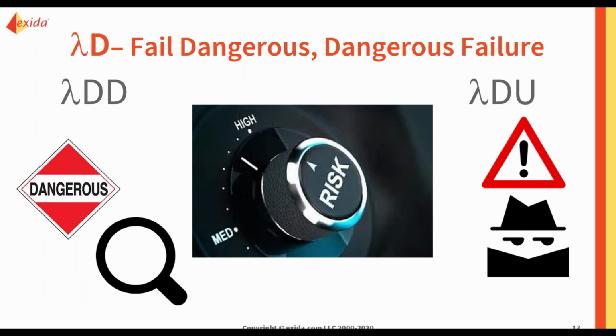Well, the dangerous is where you can't do its job. Your SIF can't jump into action if needed. So a dangerous undetected would be some type of failure that prevents the safety system from doing its job when it needs to, and it was unnoticed by any diagnostics. So if the SIF needs to jump into the action, it can't. It cannot achieve safe state if needed.